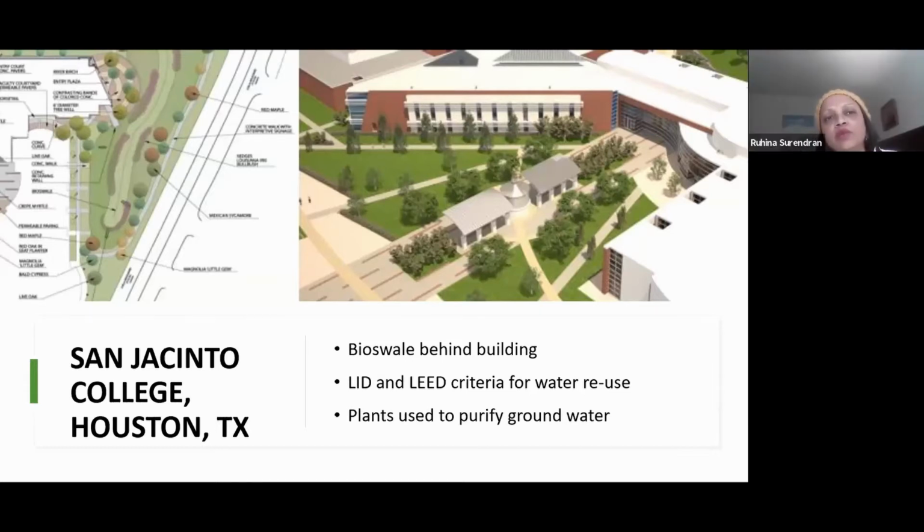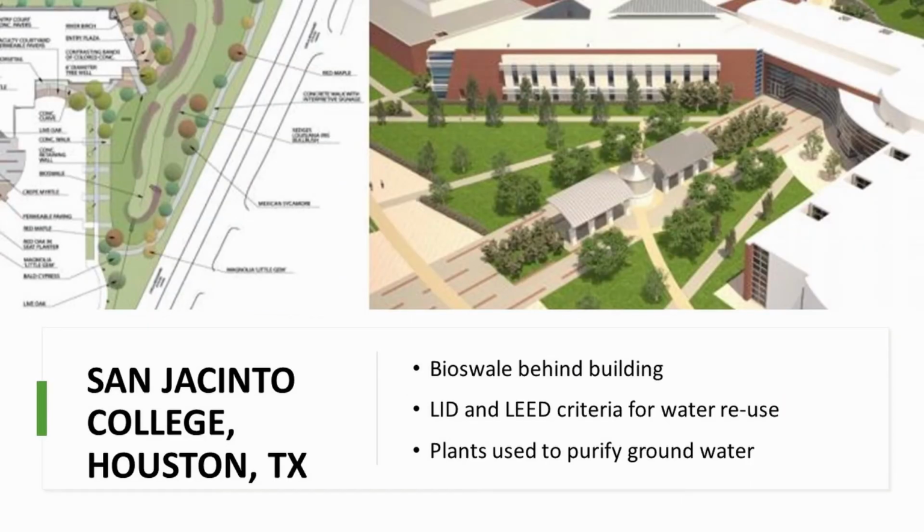Typically, when you work on a rain garden, does the civil engineer come back and recalculate the flow rates? Yes. Because I don't think they take into account the amount that the rain garden reduces the flow rate. Sometimes they design the system first and then they have you do the rain garden, but they don't incorporate that into the calculations.